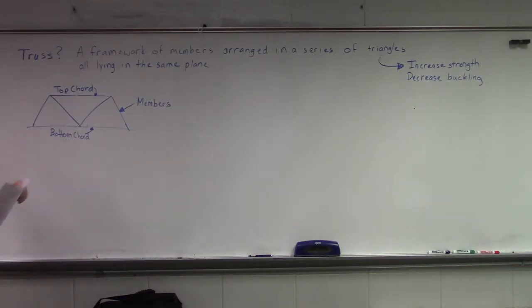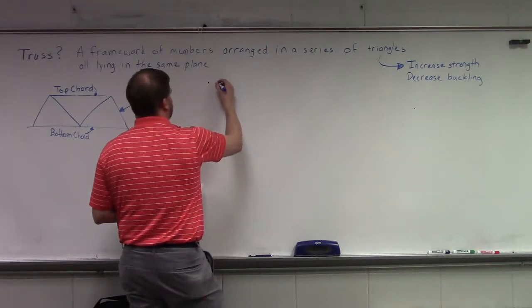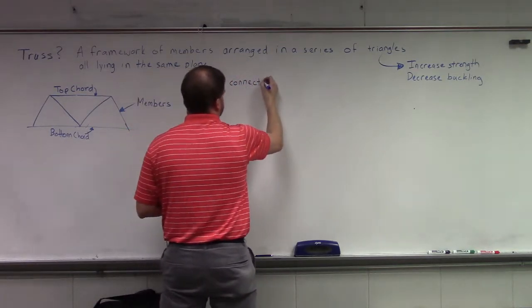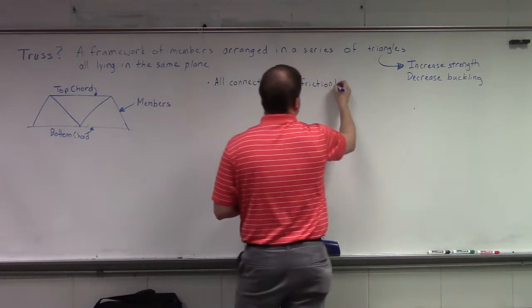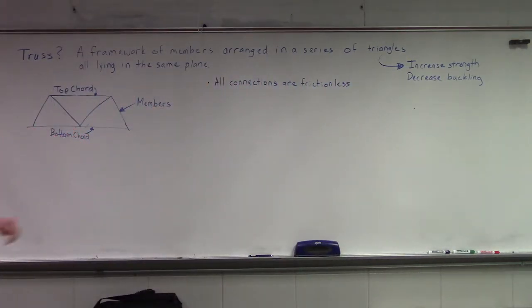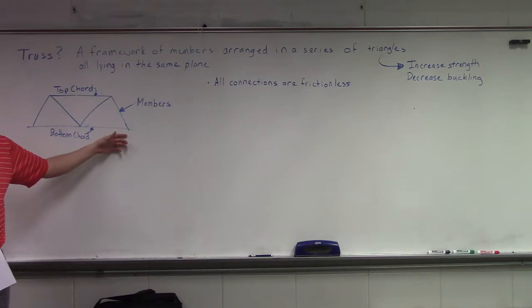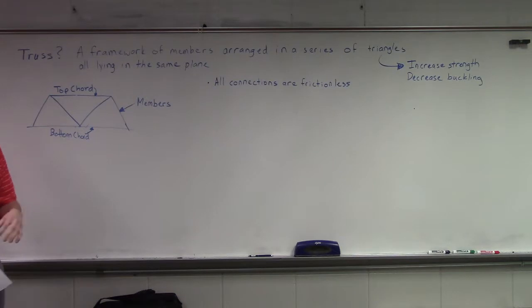So in the analysis of doing this, we have to make a few assumptions, okay? Our first assumption: all connections are frictionless. It's what we've been doing up until this point anyway, but we have to understand that, because if we have to take into account friction, then we have to know what type of material we're working with and how they're going to interact with each other. Then we have to do things like calculate the bearing area of all the pins. So we'd never be able to solve the problem. We'd be talking about the problem all day.